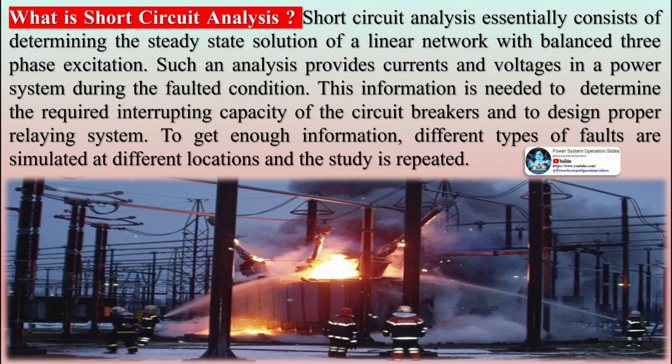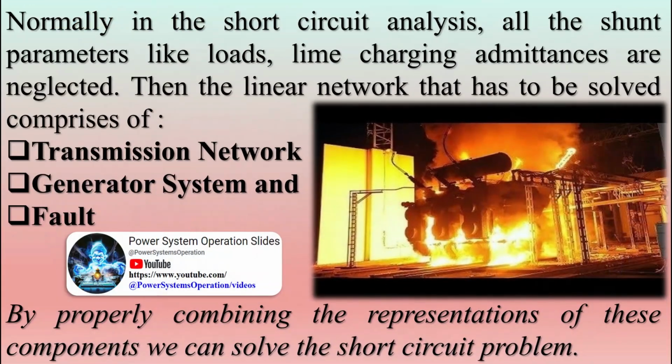NEPLAN short-circuit analysis is performed so that existing and new equipment ratings are sufficient to withstand the available short-circuit current. This short-circuit analysis can be done either through hand calculations or through known software like NEPLAN. Using NEPLAN we can perform short-circuit studies on electrical systems in a quick and effective manner in 4 steps: data collection and SLD preparation, short-circuit calculations, relay coordination studies, load flow analysis.